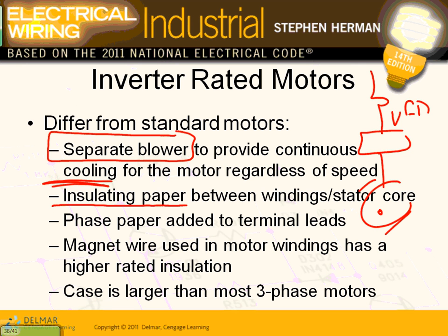They use more insulation paper between the windings. So they create what they call an inverter motor. When you read the mechanical spec and the electrical spec, they always specify inverter rated motor. Not any motor. They want a motor that's specifically designed to run with an inverter. Now, can I run another motor? It's an induction motor, but it's designed more robust, stronger, and can handle the heat.